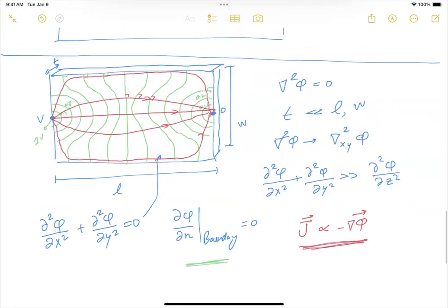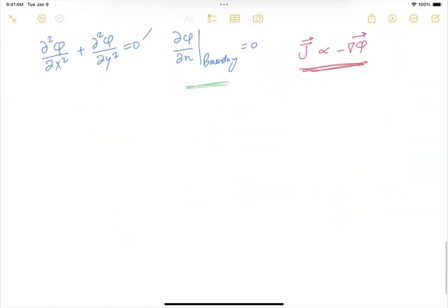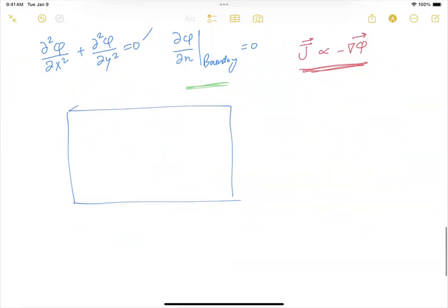So in order to get a better feel, a semi-quantitative feel of what this current density distribution in the cross-section would look like, let's take the metal, basically the voltage plane again. And now remember, one side is connected at V and the other side is 0. So if you look at the equation we need to solve, it's del square phi, basically in the xy plane, del xy square phi is 0. This is the x direction, this is the y direction.